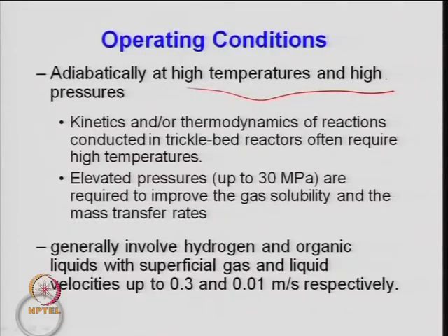Higher solubility is desired, because hydrogen is not easily soluble in kerosene. So, if you have high pressure, then the solubility will increase. Kinetics and thermodynamics, what I said, of a reaction conducted in a trickle bed reactor often require high temperature. Generally all these reactions which require hydrogen are exothermic reactions, and they also require high temperature and high pressure, which is governed by the thermodynamics.